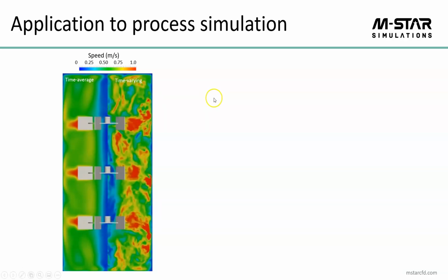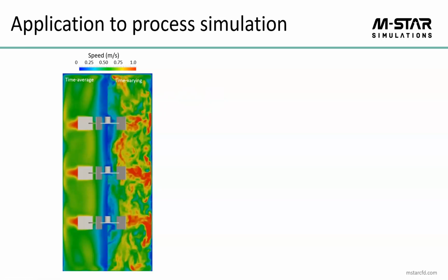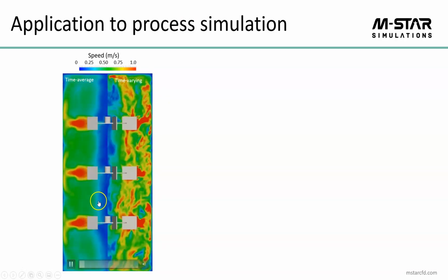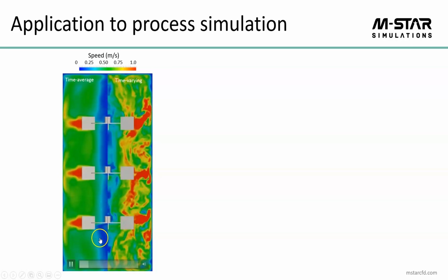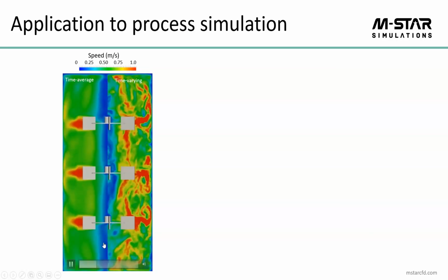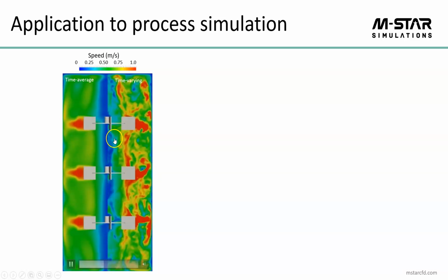It sees this strong spatial variation, energy dissipation, stress, and velocity. That's what's going on inside the tank. Lastly, the steady state solution says that, well, between these impellers, you get no flow. That is, the average velocity is zero, therefore nothing goes there. Wrong. There is a lot of flow going on in the middle of those impellers.